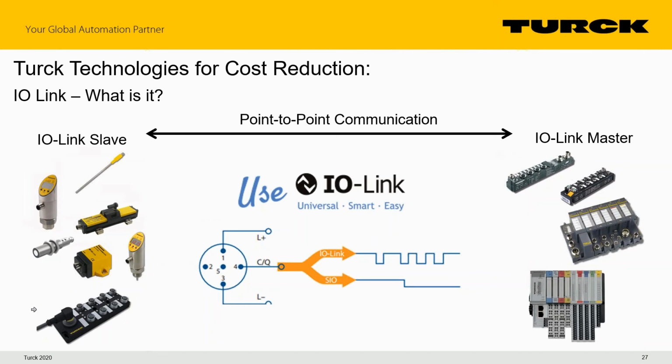I've also seen used an electro positioner, so a little servo positioner that communicated via IO-Link. And then we have IO slave hubs, like this little guy here in the bottom left. It is, as shown here, a 3-conductor connection. So it's plus and minus in our IO-Link signal going out.